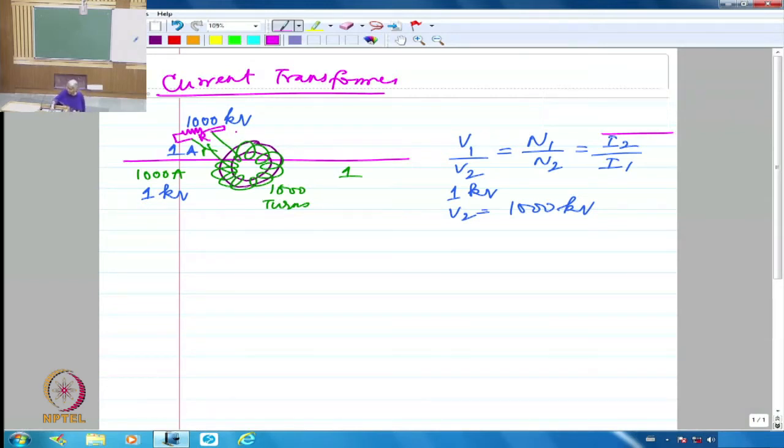So, what I get out of this will be 1 multiplied by R volts. If I measure this voltage and divide that by the known resistance, I will get exactly the current value. So, the current transformer allows me to measure the current by stepping down the current.